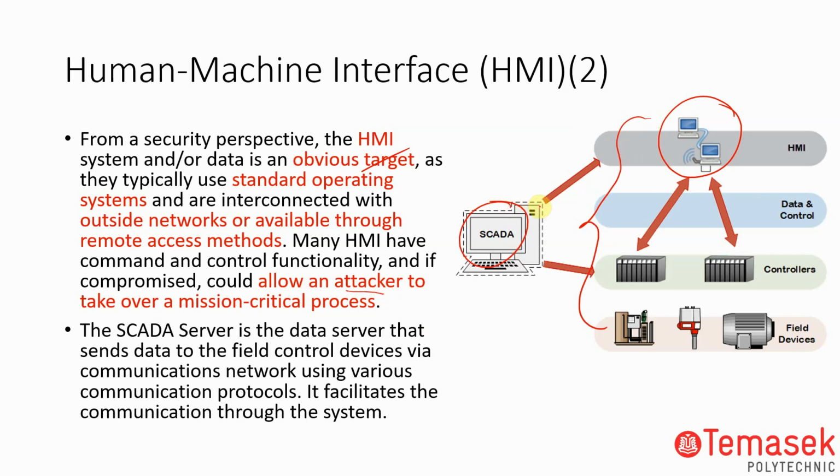So the key portion is that it's important to keep the HMI safe, which is not very safe today. Why? The main reason a lot of HMIs are not safe today, we cannot talk about all the non-industry based ones, most of the industry based ones run on a protocol called VNC. VNC by itself is not very secure.